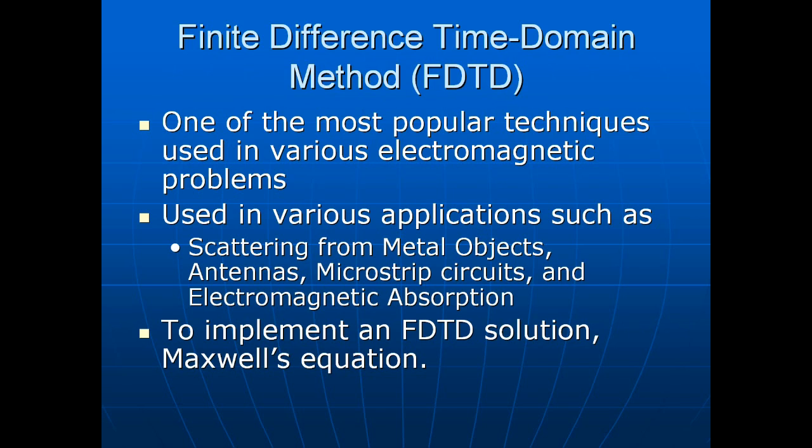In this 1D FDTD problem, the biggest factor is that the FDTD can be used to implement a general solution of Maxwell's equations. In order to do that, a computational domain must be defined first. The computational domain is defined as the area where the simulation will be performed. This is where dimensions become vital when it comes to simulating. Then, at every point in space, the electric and magnetic fields have to be determined within that computational domain, as well as the material that will be used within each cell.